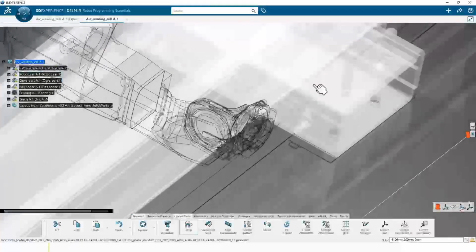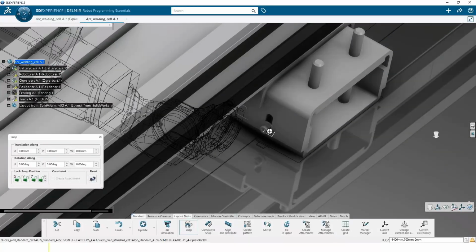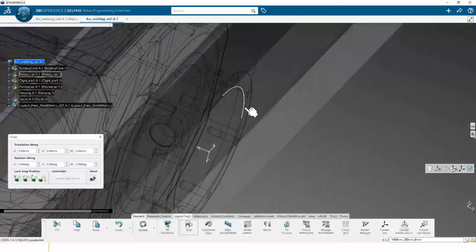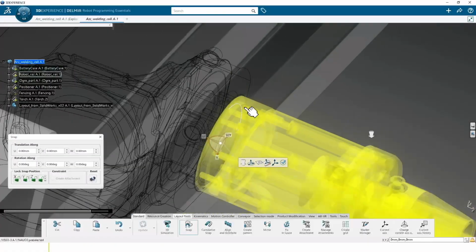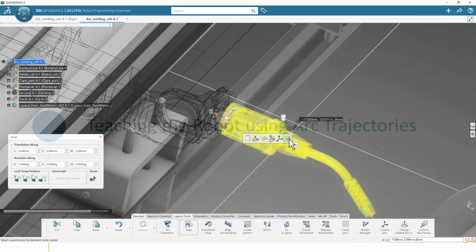As far as the tooltip goes, again, the end of the robot is going to have a base port defined on it. And if we simply select that face, there are indexing components in there that'll fit this thing perfectly and seat it into place. And then from that point on, everything is based on the tool center point as far as the robot's movements and positions. It really is just that easy.